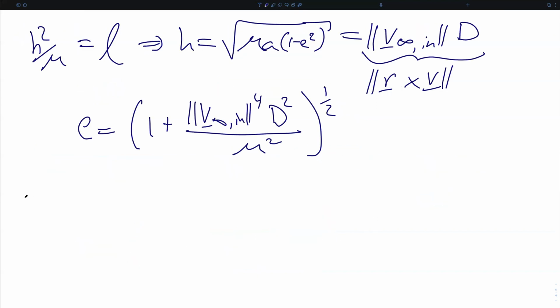At periapse, we have an orbital radius of r sub p, which is equal to the orbital radius when nu is equal to 0, which from our conic section expression we know to be equal to a times 1 minus the eccentricity. Note that all of the sign conventions work out here. A is a strictly negative quantity. E for a hyperbola is strictly greater than 1, making 1 minus e also strictly negative. And so this will be a strictly positive term.